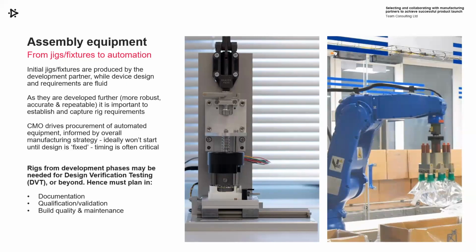Ideally, you won't be investing in high-end assembly equipment until the design is fixed, but timing is often critical, and sometimes the assembly equipment can take a long time. The lead times are long, so you might need to be pushing the button on those even while you've still got design changes in mind. So be careful there, think carefully.